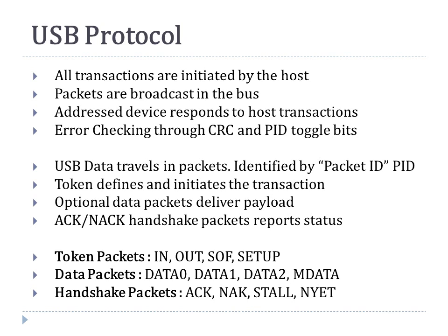Now USB is like a packet switch network. It uses packets to send data, and each packet has a packet ID, and there are several kinds of packets called token packets, which defines what kind of transfer will happen. The next is the optional data packet, which delivers the payload, and there's a handshake packet which reports the status.